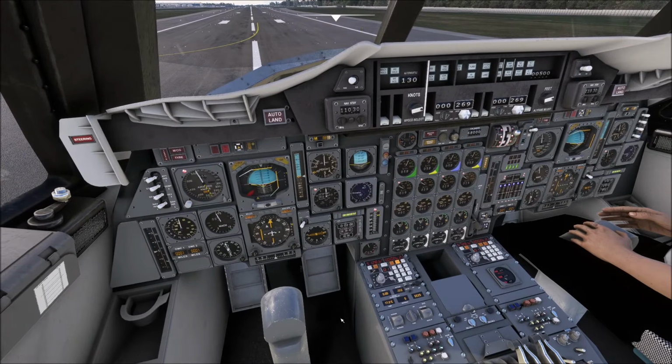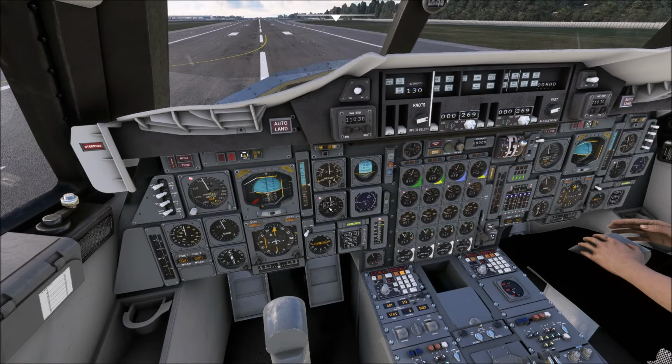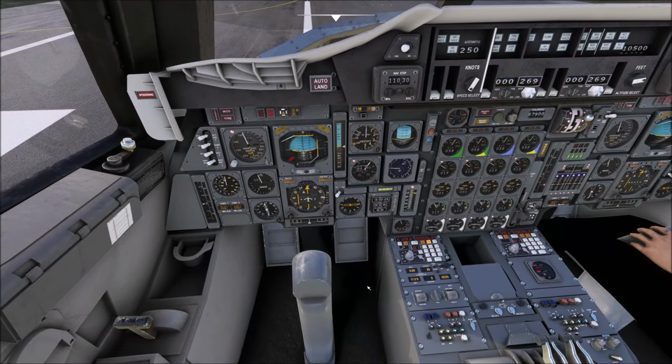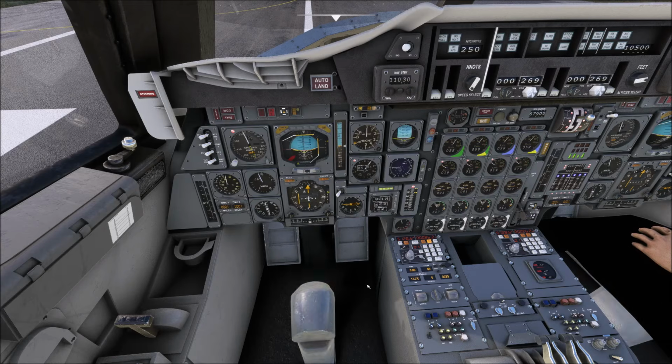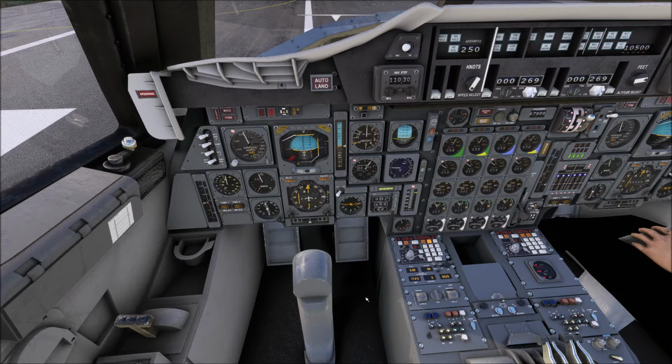So, series of set jobs you do in any aircraft. Zero the altimeter to local air pressure. I'm also going to set up the autopilot, get ready so it can take over after takeoff, and that'll give us our starting point. 250 knots will do. We'll set first for 10,000 feet. Give the controls a full and clear.